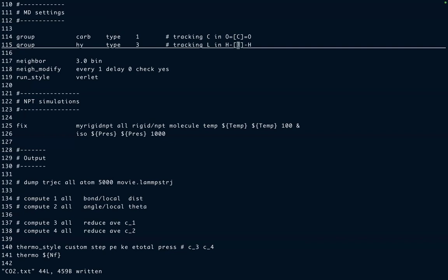To enable the computations from the OCTP plugin, it is crucial that these groups are clearly specified at the beginning of your simulation. If the groups are not correctly specified, the OCTP plugin fails to recognize which positions to compute and could thus result in a crashing of your simulation.